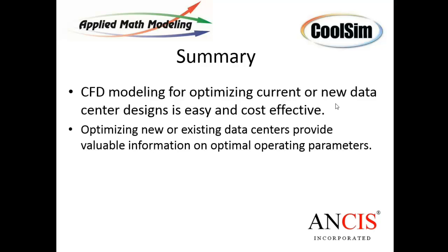The corollary is, do you feel a simple kilowatt per cabinet is sufficient to give accurate results? I noticed the rack inlet temps are different than the server inlet temps. Is that because there's zero internal cabinet recirculation? The answer is yes. In a first pass analysis, again, you can always add more detail to these things, but be careful of the detail because you can get lost in it.